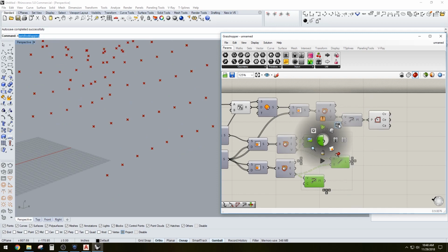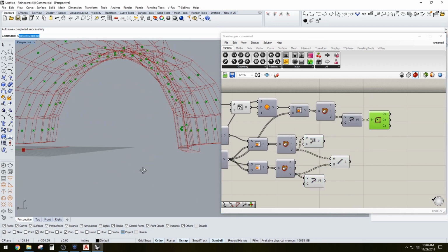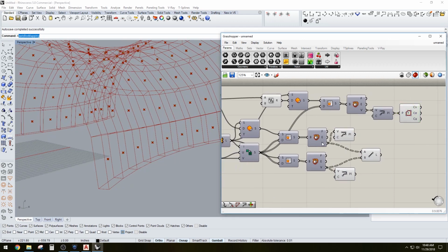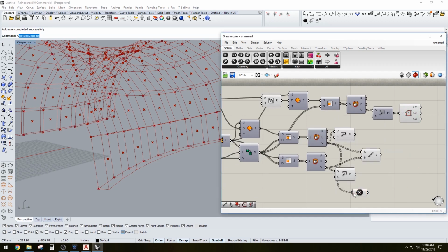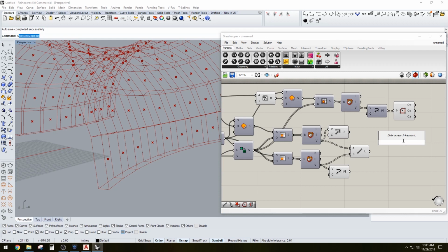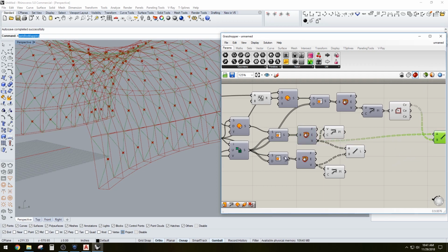Now we have that point in the middle, and we have these points in the back, and then these points in the front. So these points on the outside are going to go all to one point, and all these points on the back are all going to go to one point for an X space frame. So I'm going to delete these so we don't have redundant points, and let's go ahead and create a line from point A to point B. So the point A is going to be here, and the point B is going to be that center point. So we have that X,